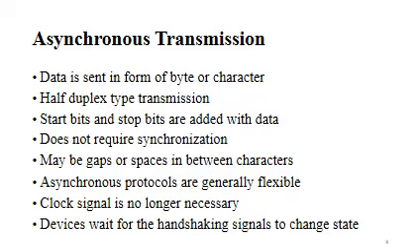The RS-232C protocol uses an asynchronous scheme that permits flexible communication between computers and devices using byte-sized data blocks, framed with start, stop, and optional parity bits on the data line.